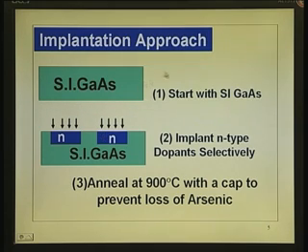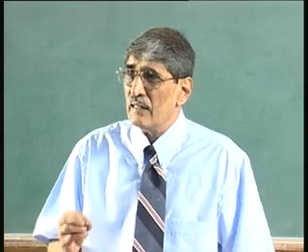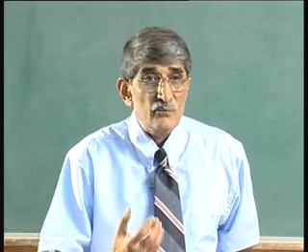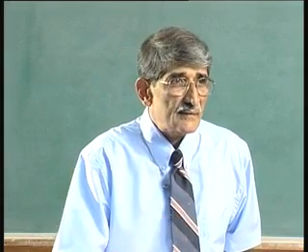Okay. Now, the story is not over there. You implant the dopants selectively here and leave it, you do not get anything, because this implantation is done, particularly implanting to gallium arsenide, at high energy. Implanting onto silicon requires certain energy, and it requires more energy to implant at a certain depth, because silicon is lighter compared to gallium and arsenic atoms.